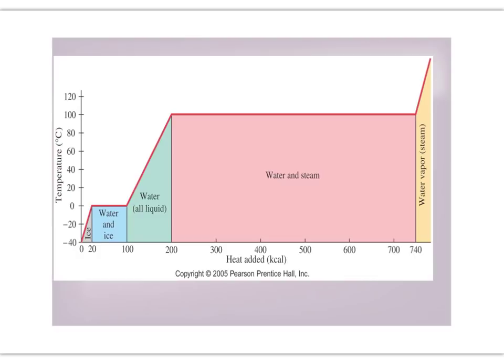Going back to this phase diagram heating curve, on all of the line segments for which we're raising temperature, here, here, and here, that's going to go with the equation Q equals mc delta T. And so the mass is going to stay the same. The specific heat, you got to pay attention to that. That's trickier. The specific heat of solid water, ice, is different than it is of liquid water, which is different than it is of gaseous water, steam. So you do have to make sure you're using the specific heat for the correct phase. And then the change in temperature, remember, is also just going to be during that segment.